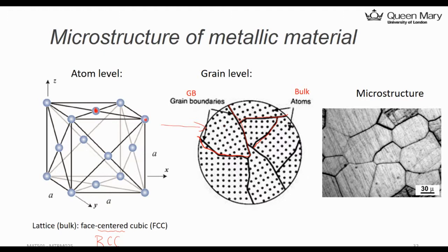Actually, that's facilitated for the atom to travel. But also the atom can travel within a grain. So that is called bulk diffusion. If the atom goes through that region, that's the grain boundary diffusion. The atom travels through the channel and goes from here, through the channel, to another grain, something like that. Okay? So that's the microstructure of metallic material. That will govern the final behavior of the material at high temperature, high stress, at a certain amount of time.